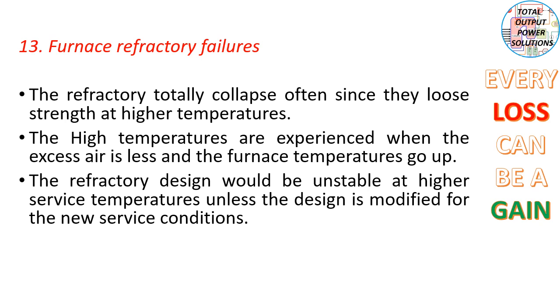Then furnace refractory failures. The refractory totally collapses, often since it loses strength at higher temperatures. The high temperatures are experienced when the excess air is less and the furnace temperatures go up. The refractory design would be unstable at higher service temperatures unless the design is modified for the new service conditions.